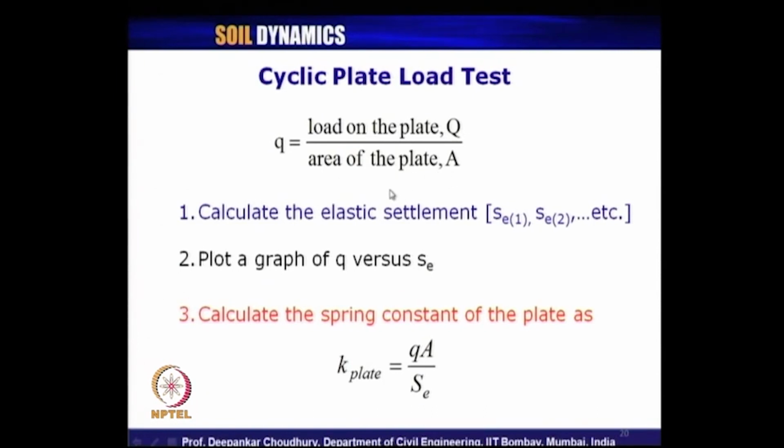Generally, square type of plate are used for plate load test. You are aware of the static plate load test. So, the same thing is used in case of cyclic plate load test. Only change is, instead of a static loading, we will apply load in cycles. We will see that. So, what are the steps?